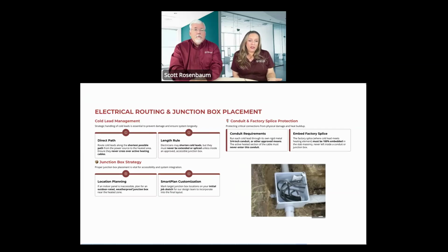So that's the 20-foot lead with the 120 and 240 volt systems. If you are doing commercial projects in the 208 or 277 volt, you do have a 50-foot lead wire, a little bit longer, which is easier when you have very large commercial buildings to get into with your cold leads. So route that to the shortest path possible, telling us ahead of time if the power is coming from the building on the left side or the right side, so that we make sure your heating cables never cross your lead wires. That lead length, though it's 20 foot, you can shorten if you don't need all that 20 foot, but extending it has to be in a junction box and it has to be watertight.